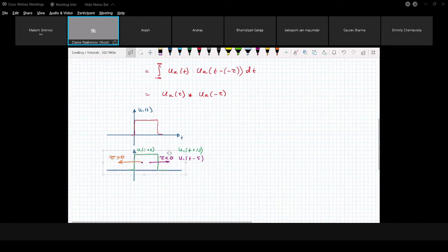We just need to evaluate what happens in the range of our signal, because if the copy is outside this range, for example for a delay greater than T/2, what will be the result of correlation? It will be 0, because they do not overlap. There is no correlation.